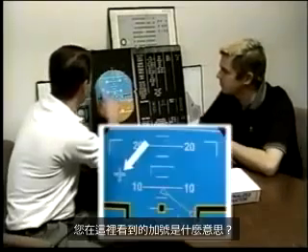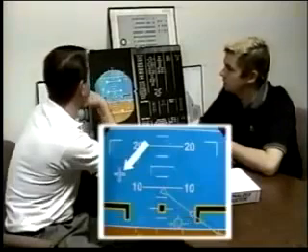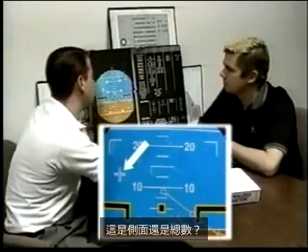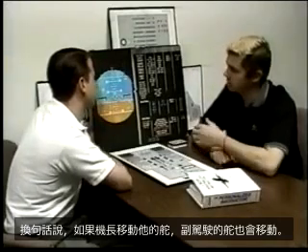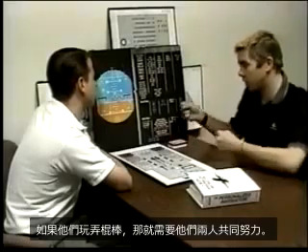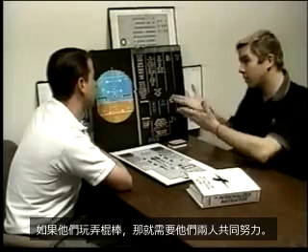What about the plus sign you see here? What does that represent? Side stick's order indication. Is that one side or is it the sum? It's a sum of the two. So in other words, if the captain moves his, the co-pilot's will move as well. And if they play around with the sticks, it takes a sum of both of them.